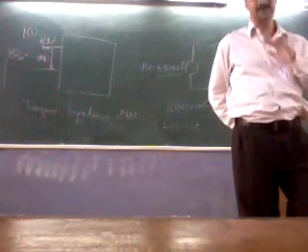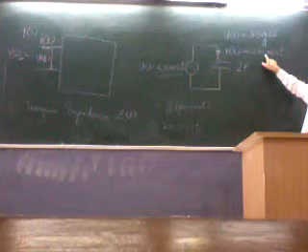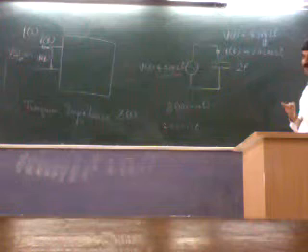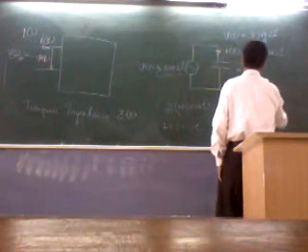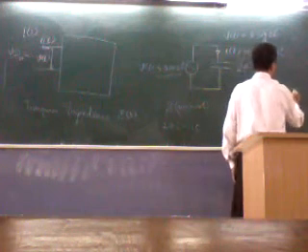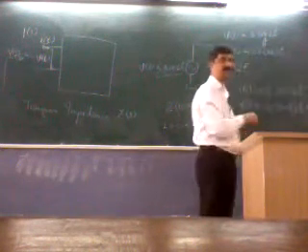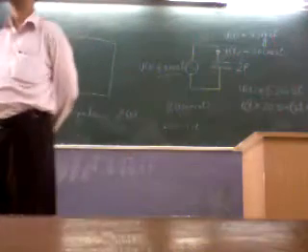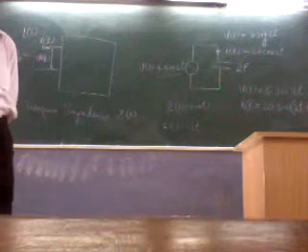So rather than carrying a misconception of tan because we wrote it as cos 2t, I will rewrite it in a different way. V(t) is 5 sin 2t and I(t) I can write as 20 sin of 2t plus something. What is that? cos t is sin of t plus 90 degrees, or pi by 2. Right? Okay.